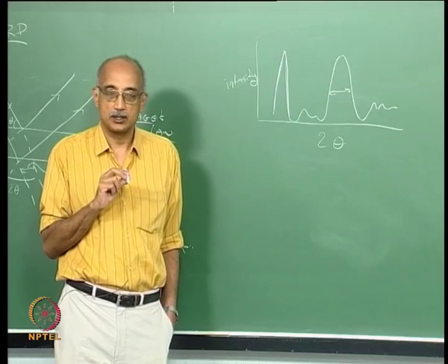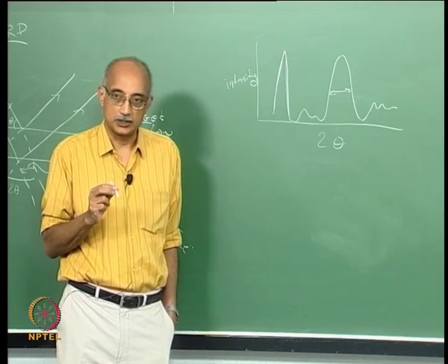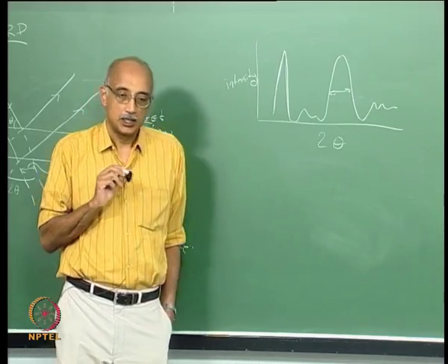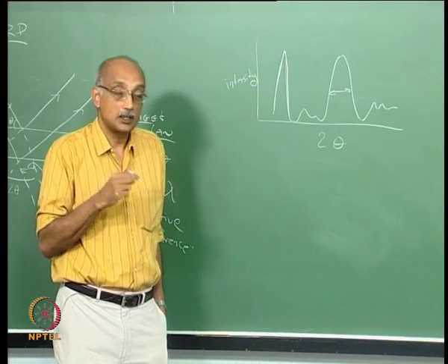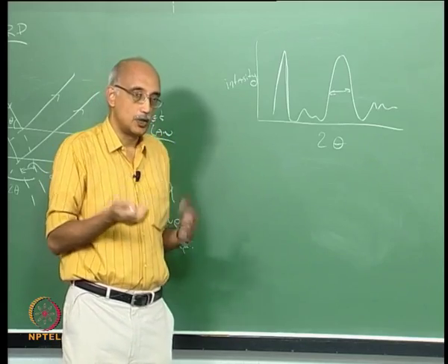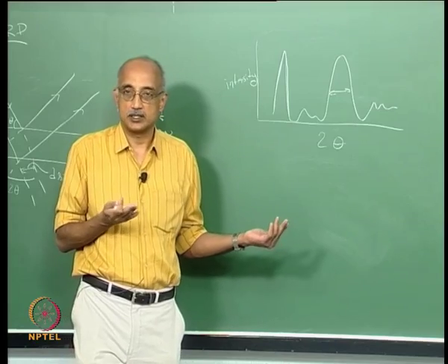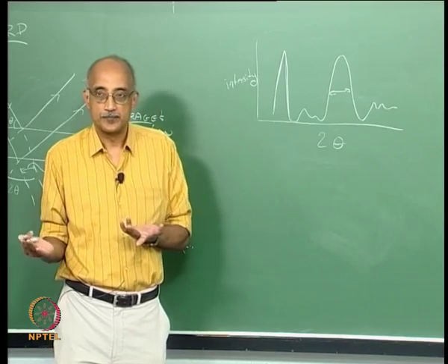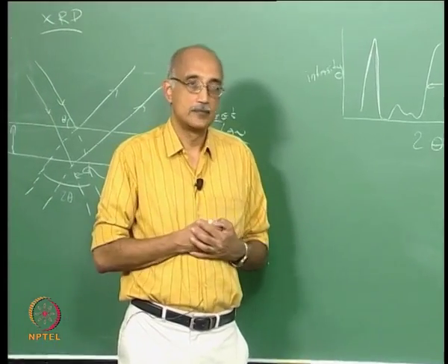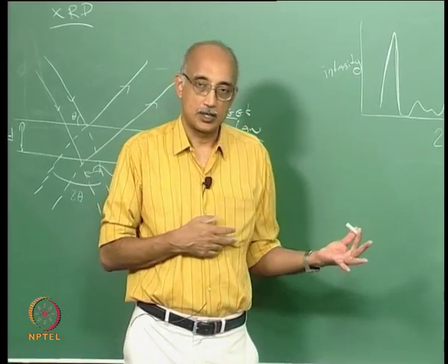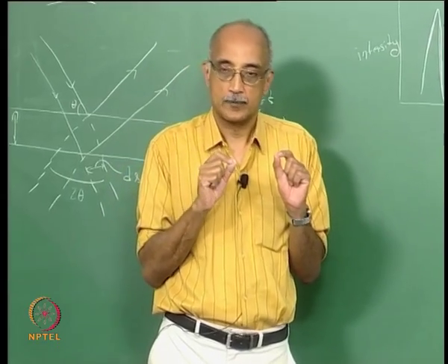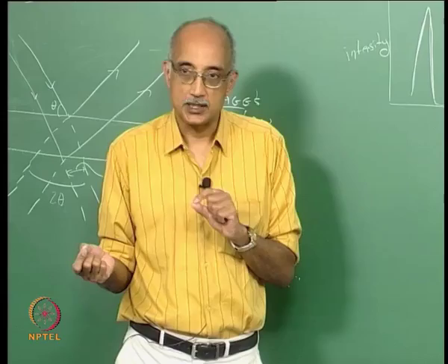about the crystallinity of the material as well as the size of the material, and also the specific dependence of intensity and 2 theta is a function of the material itself, the chemical composition of the material. So, for example, alumina will have a very different XRD signal compared to, let us say, silica. So, if you want to distinguish between two essentially crystalline materials, alumina and silica, you can do that by using XRD, or if you are just looking at the chemical composition, you can also use other methods such as SEM,